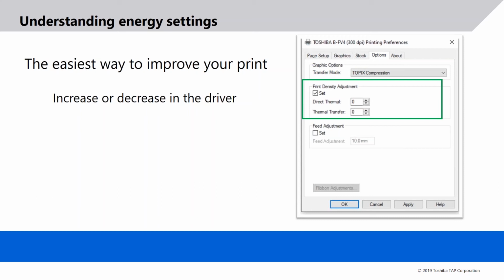If we're wanting to get nice sharper edges, we might find that backing the heat off a bit helps with that. So it's really just a matter of trial and error. There's no set rule. It's just a matter of seeing where you can get the best print at the lowest temperature. You always want to try to use the lowest temperature possible before the print is compromised, and that's because it has benefits for your printer, which we'll be discussing momentarily.